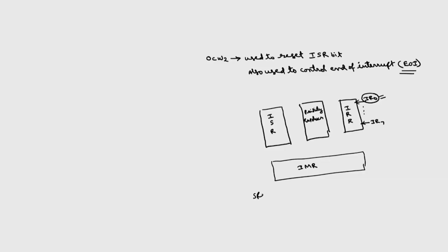In case of specific EOI, as the name implies, we specify the bit which is to be reset in the ISR. Specific EOI will be programmed by the OCW.